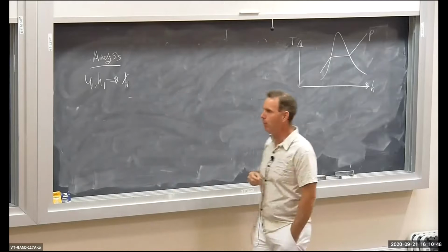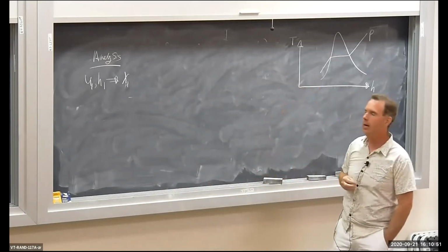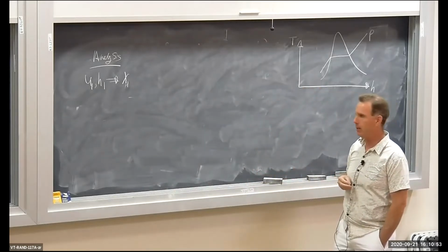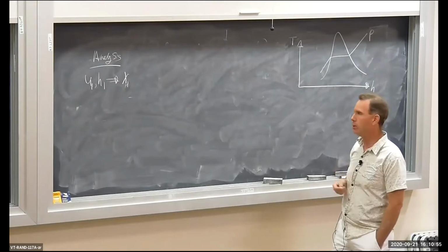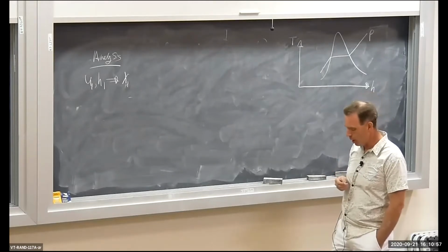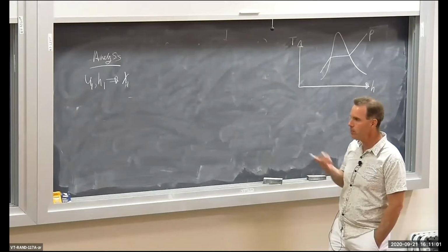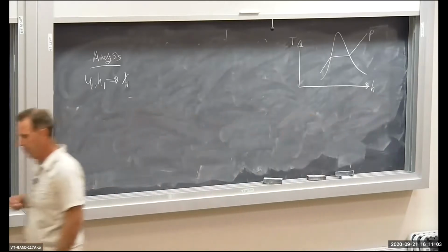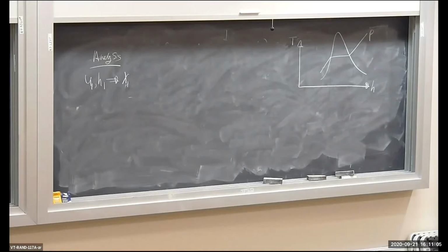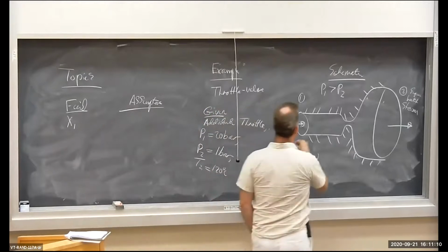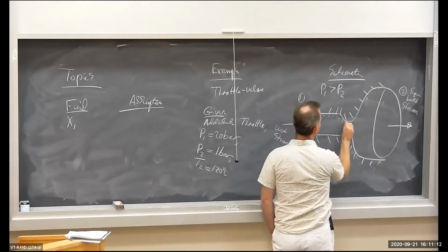So really, the problem should be driven by trying to find the inlet specific enthalpy, H1, or internal energy, U1. So what equations have H's or U's in them as far as open systems? Oh, let's define our system. So this is clearly an open flow device.